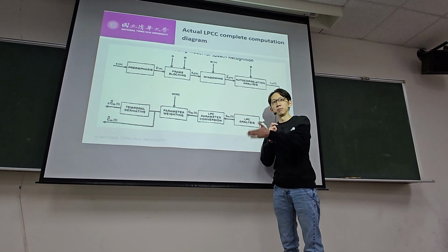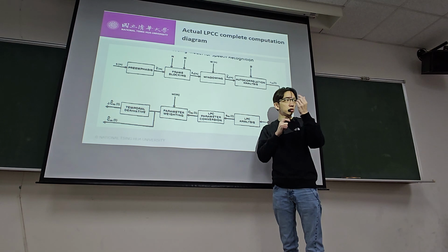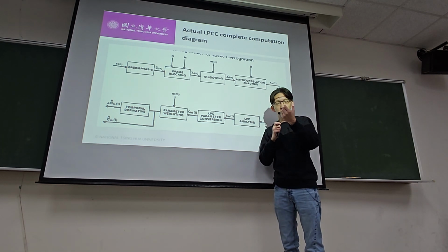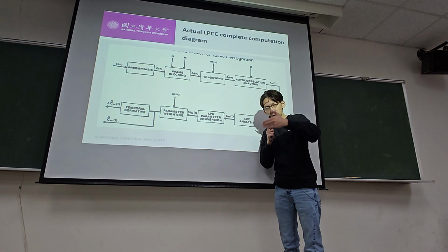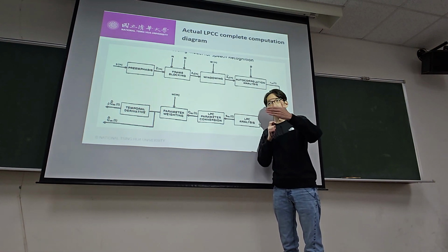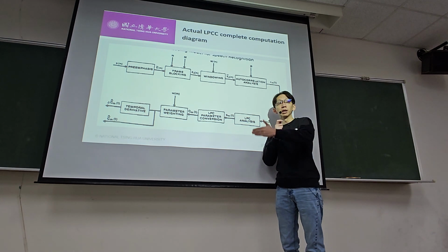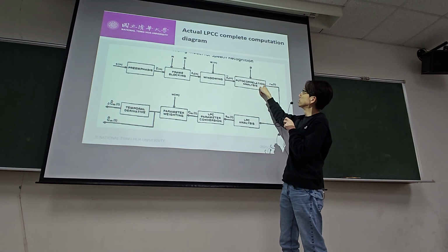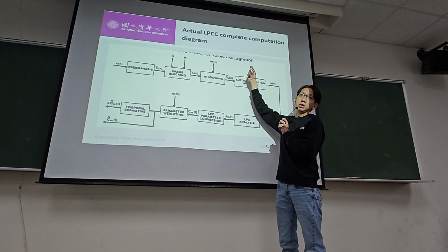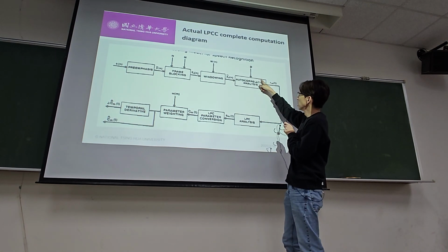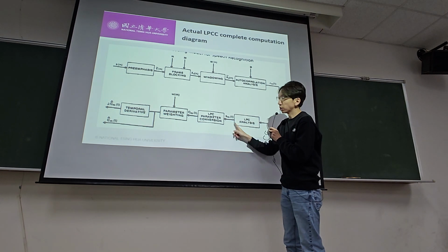One way is to segment out a small piece of the signal, and by deduction it becomes a normal equation. That normal equation can be computed recursively using the autocorrelation function. So using autocorrelation analysis, depending on the order, how many past samples you want to use for linear prediction, you get the LPC coefficients.